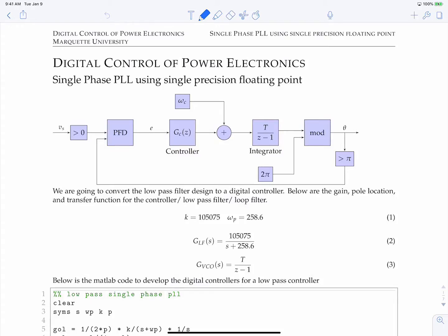Now, if you're using a processor that doesn't have a floating point unit and you're using floating point numbers in your C code, unbeknownst to the writer most of the time, when you go to compile, the compiler is actually going to realize, hey, you don't have a floating point unit on this processor, and load a library to do these calculations. And the net result is that, for instance, a simple addition may require 10, 15, 20, 30 instructions just to do one addition. And if you think about it, that adds up pretty quickly because all these filters are a lot of addition and multiplication. And that's just for one filter. If you have multiple, this adds up very, very quickly.